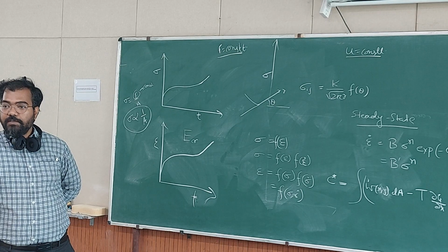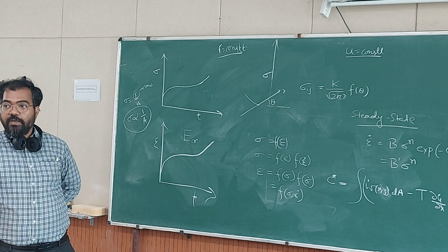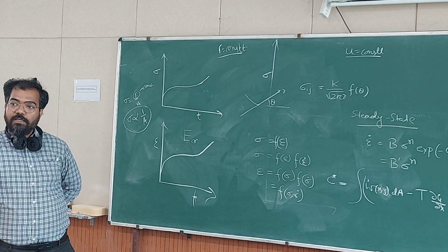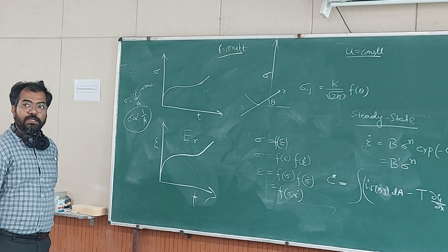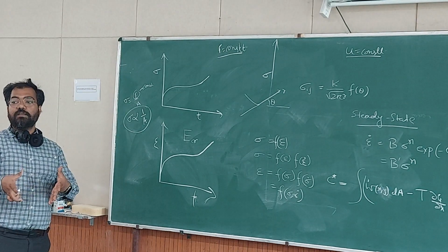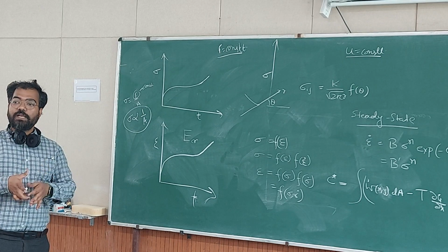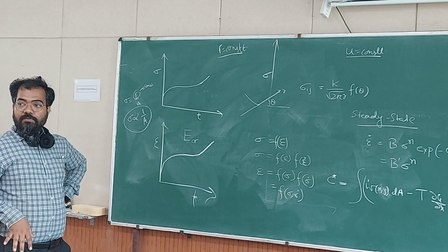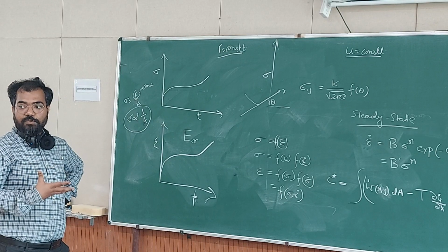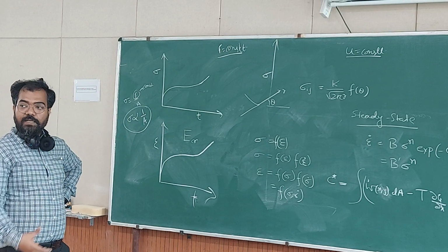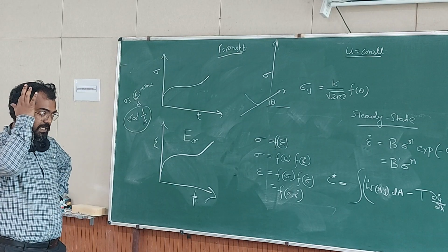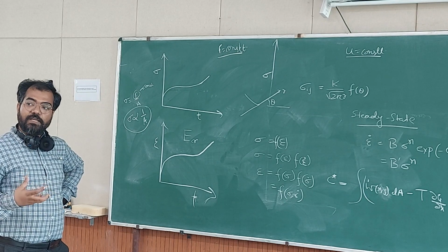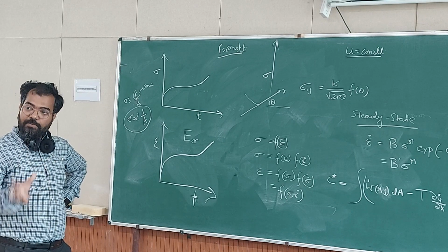It was not really the objective to find out k, because nobody knew that there will be one value which will be common in describing the stress. So the objective is to describe the stress and strain field as close to the crack tip as possible. Then plastic zone developed and it became bigger, so this theory was not valid, so then became a line integral, and this line integral, which is J integral, can be used to describe stress and strain at the crack tip in the plastic zone.